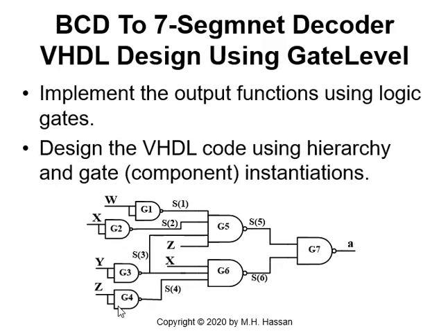G1, G2, G3, G4, and G7 are 2-input NAND gates, while G5 is a 4-input NAND gate, and G6 is a 3-input NAND gate. And we see a vector called S, S from 1 to 6. Those are neither inputs nor outputs, so we call them intermediary signals.